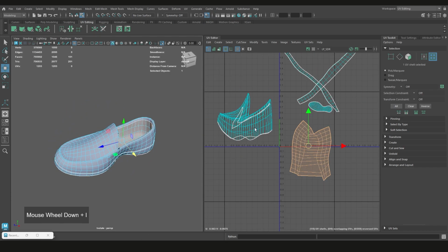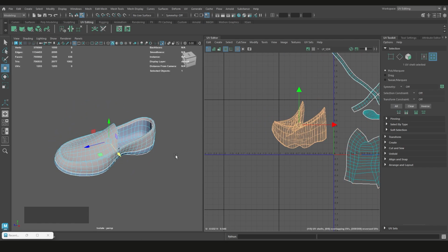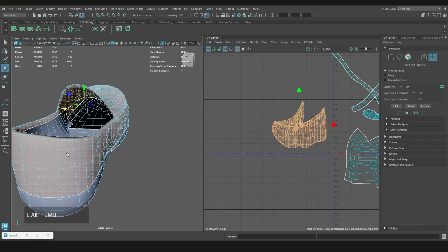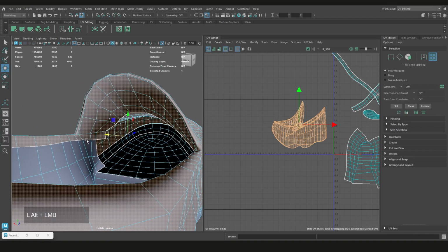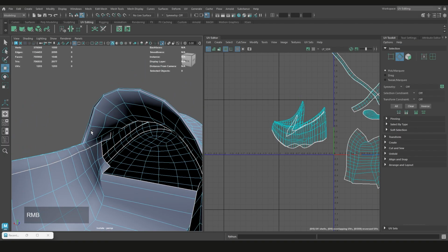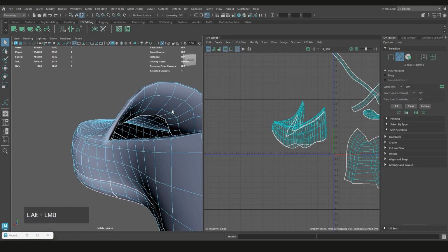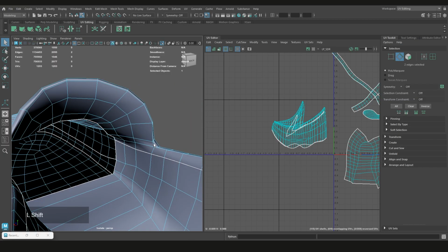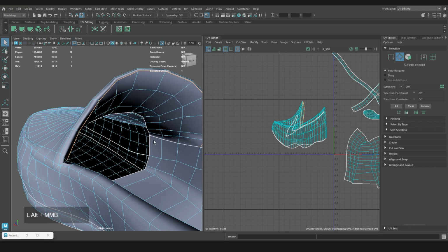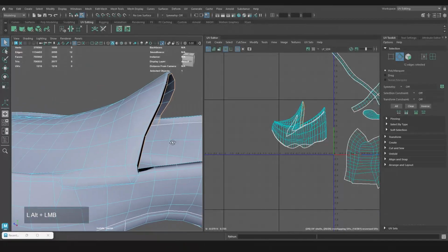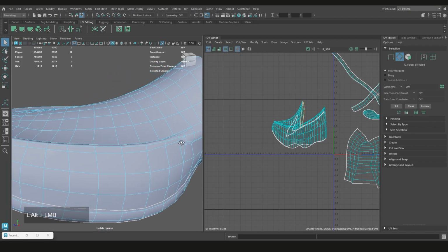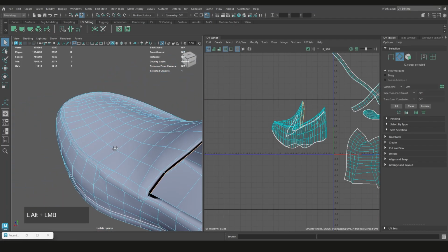This piece isn't important, so we won't worry too much about that. And so here we're going to have to cut as well. So let's see what we have here. I think I'm going to cut this piece here, so the edge. So from here, I'm going to press Q to get out of that. Shift click, shift double click. Okay, and shift click, and then I'm going to go to cut. So that piece is now separated.